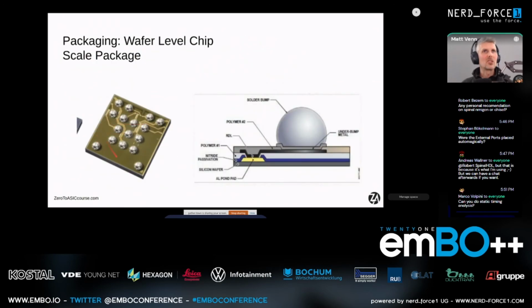It's going to be packaged in wafer level chip scale package, which is admittedly quite small, but is doable for hand assembly. I've done a bit of BGA. It's not too bad, especially with an oven. And it's good for signal integrity. So there's some people doing radio stuff, and for radio stuff, it should be great. Although we're still testing out the GPIOs, how they're going to respond to high frequency stuff.